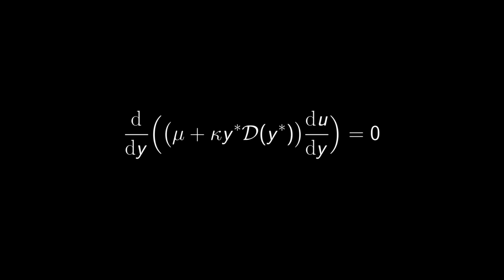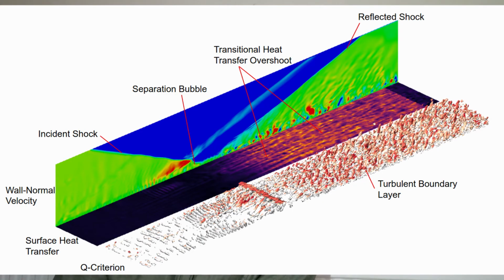Now, within the framework that I use, these complex interactions near a boundary are considered to be somewhat universal. So, instead of using a large number of cells near the wall, I save on computational costs by simply assuming that they are of some form and that they interact with the fluid outside the boundary layer in a very predictable manner. Now, the core of my research here is how to model these interactions. For subsonic flows, these interactions follow some quite regular patterns, but there are a few elements of fluid flows at hypersonic speeds that can challenge these interactions.